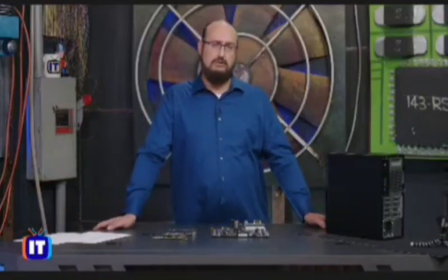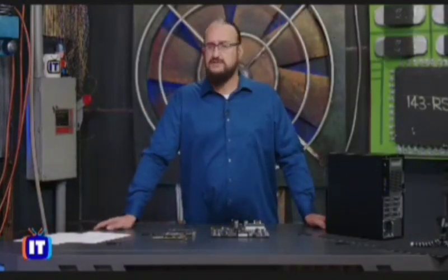But one of the limiting factors that Ronnie was mentioning on PCI is the fact that it used, if you've been following along in the series, parallel communications. And anytime you have a parallel communication, you do run the risk of having crosstalk and interference. The other is that only one device could control the PCI bus at one point.